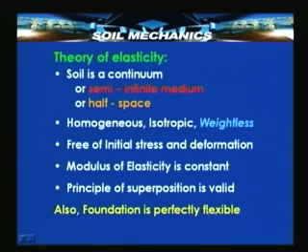But finally, a very important assumption that we shall be making is that this foundation is flexible, perfectly flexible. The importance of this has already been stated, that is, when we have a flexible foundation, we have uniform contact pressure, and all the derivation, all the theory, all the methods that we shall be seeing now are all valid for uniform contact pressure at the foundation soil contact.